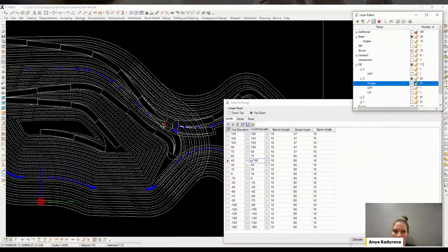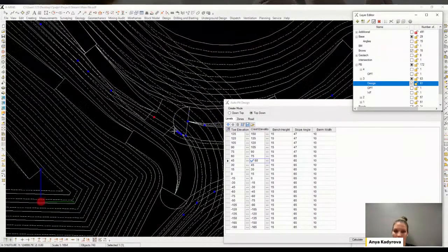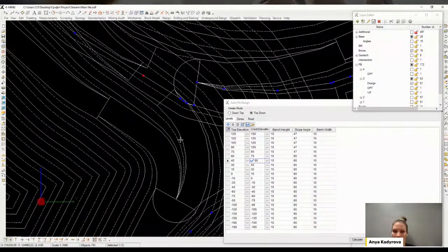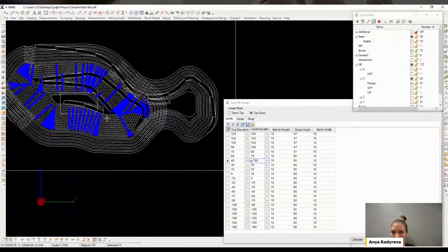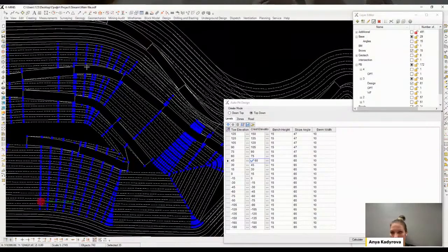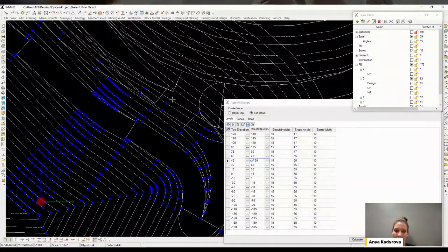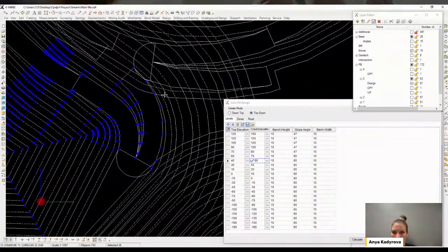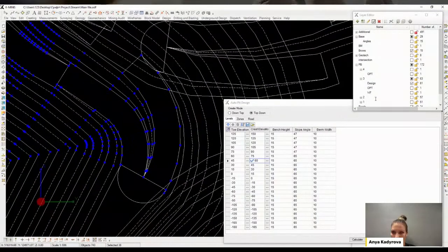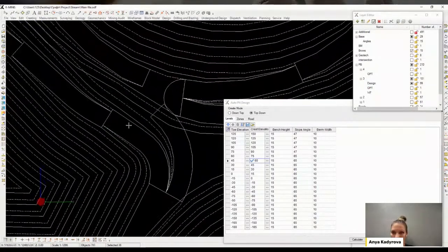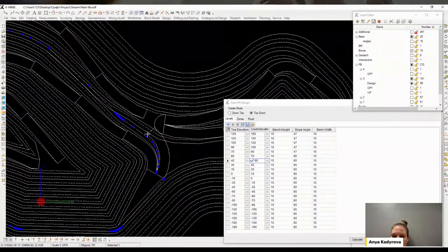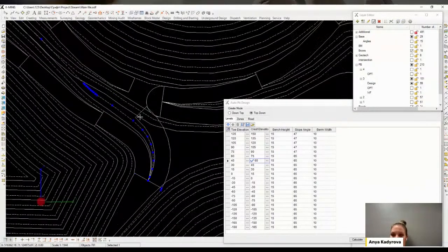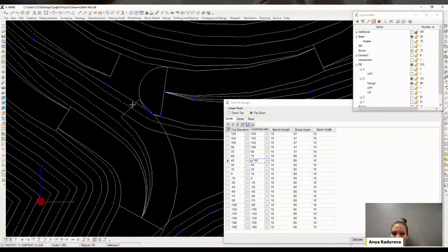In the process of automatic design and design in general, we should remember the basic concepts of productive design. So roads should be as straight as possible with a minimum number of bends and turns. It's better to arrange horizontal inserts only at the junction of several roads or at sharp turns. And also, it is necessary to minimize them, and this configuration will allow achieving optimal performance in the removal of rock mass by dump trucks.